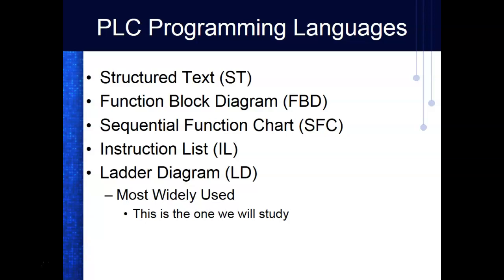So 5 languages, and the application that we're using, called RSLogix 500, only supports the last one, which is ladder, and it's by far still the most widely used. The other languages are function block programming, or FBD, structured text, sequential function chart, and instruction list.